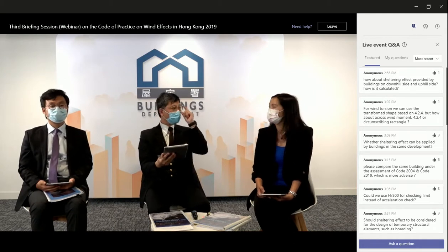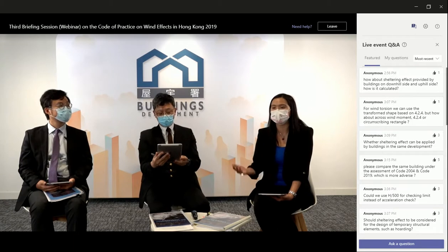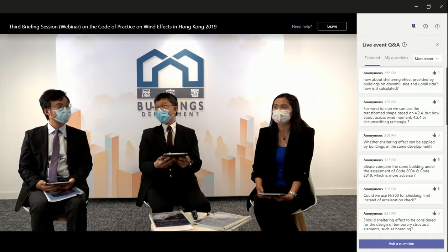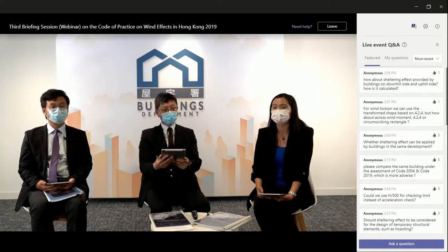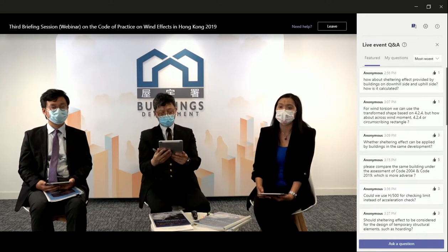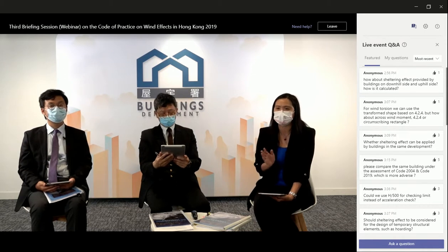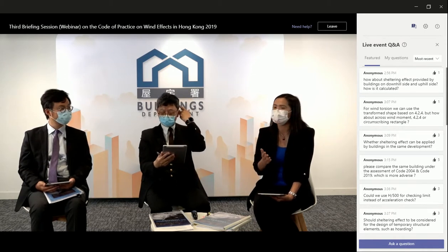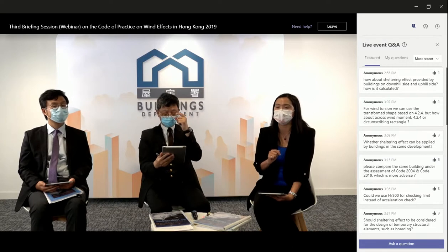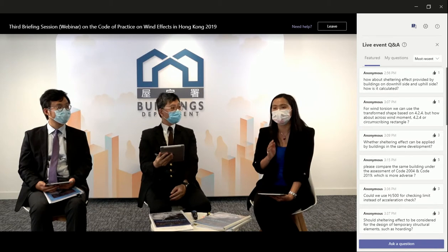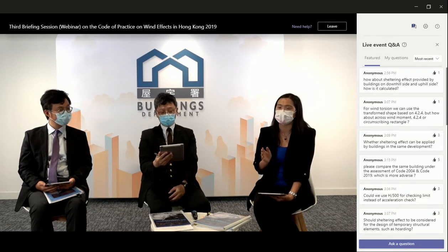Actually, during the consultation of the wind code, with the help of a number of RSCs, we had some sensitivity analysis for a few real projects. These real projects were designed to wind tunnel test results. So we have the wind tunnel test result and the building form. We carried out a study to estimate the wind load based on the 2004 code and the 2019 code, and then compared against the wind tunnel test results.